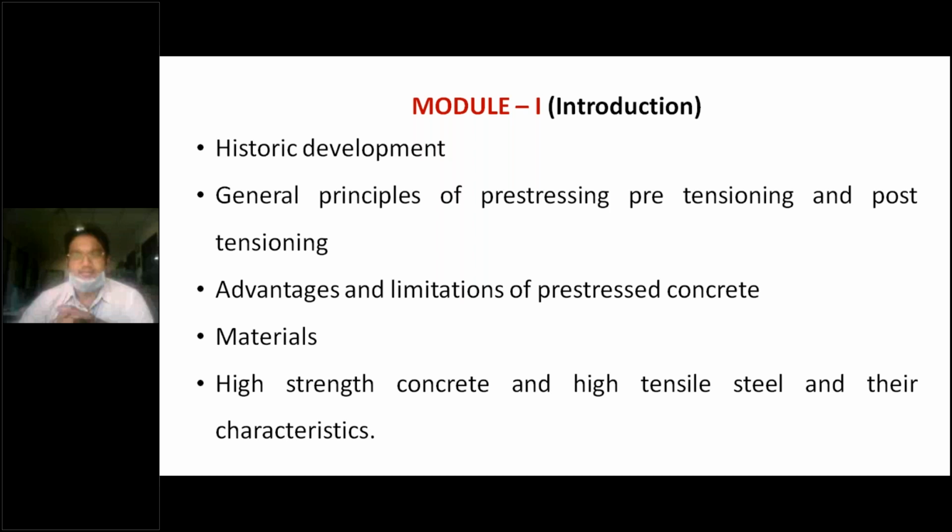Sir, is this concept applicable for cantilever structures in buildings or bridges? Exactly. For all infrastructure projects nowadays, they are going for pre-tensioning along with post-tensioning, especially for the pre-cast elements. So even for cantilevers, this pre-stressing technology can be used, where they provide tendons above the neutral axis.